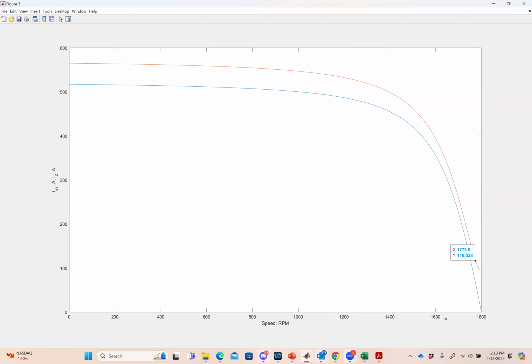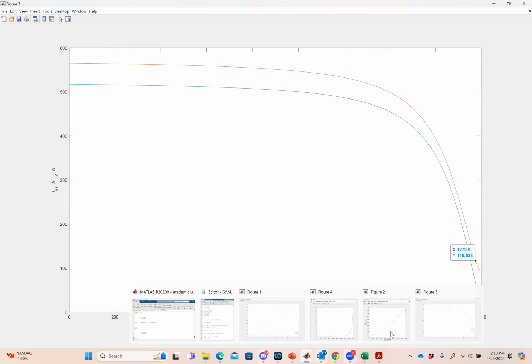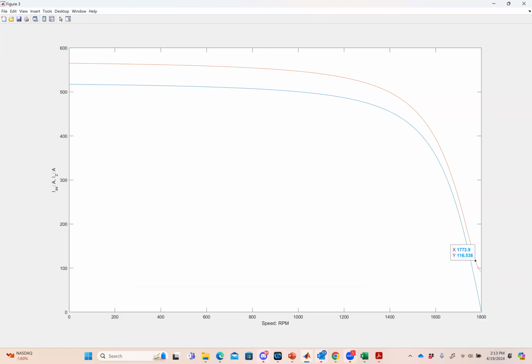It's fairly easy to analyze those circuits. But one thing that's important, and that I want to end on, is that I'm also showing you pretty old school problems. Because if I look at the way this motor works, I made this motor so that at full speed, no load, it's at 1800 RPM. At full load, it's at 1773 RPM. That's a pretty limited range in which it wants to operate, right? There's basically everything below 1773 RPM that's kind of off the table for me.